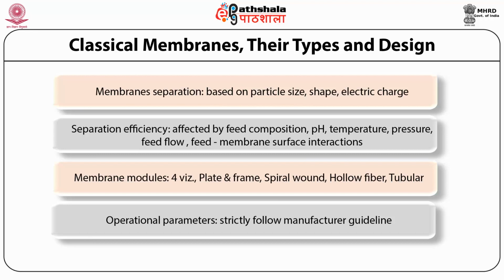The main problem of such systems is the rapid cake layer formation over the membrane surface, which is directly responsible for membrane flux reduction, as shown in figure 1b. This problem was overcome in the cross flow design, in which a single feed stream is subjected to the membrane parallel to its surface in a closed system at higher pressure with turbulent flow that divides the feed into two streams, namely permeate, the molecules which have passed through the membrane, and retentate, in which the membrane has retained the molecules.